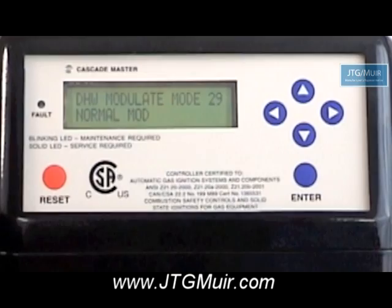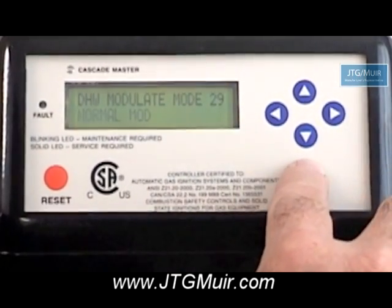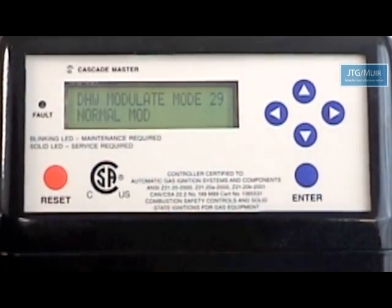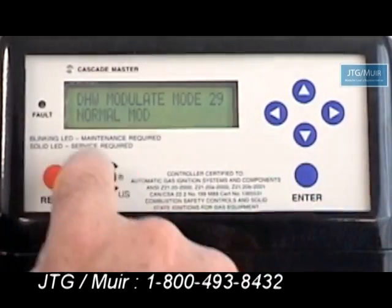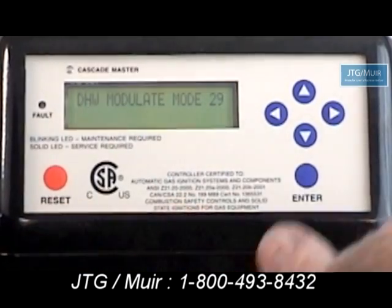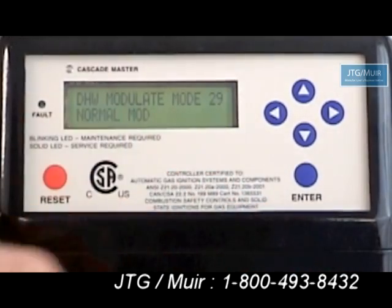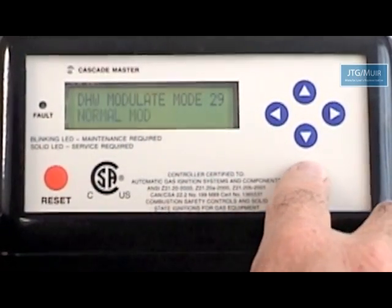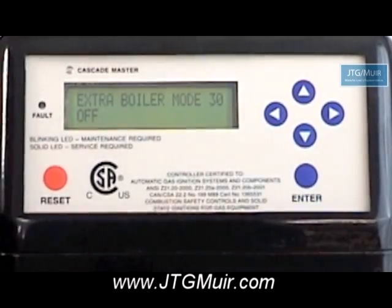If I choose to have it modulate in a stepped modulation similar to the heating system, then I hit the enter button. It says normal modulation, which is wide open. And I can hit the low modulation, which is a step modulation similar to the heating system, or I can go back and have normal modulation, which is wide open from the start until it hits set point. Once again, I hit the enter button and I index to the next function.